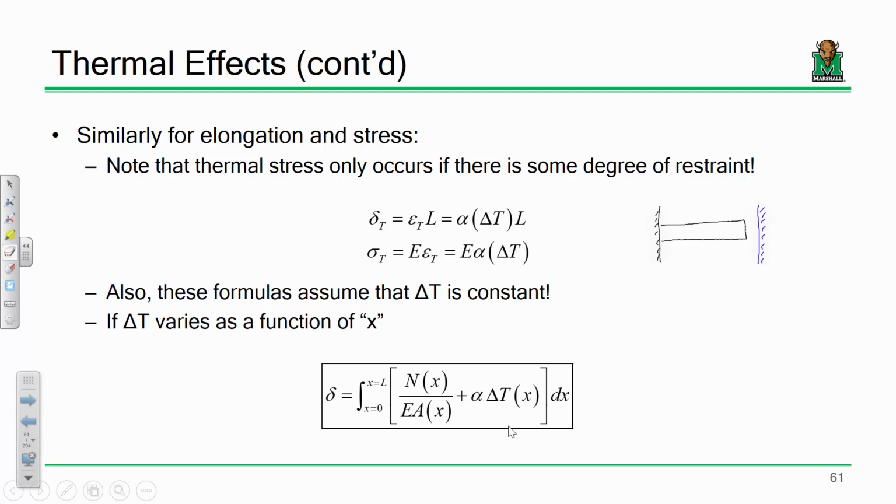This is my expression for deflection. Okay? Now, you agree I can split this up into two integrals, right? The integral of the first fraction plus the integral of this, right? Let's look at that. Does our bar in this problem have a constant area? Does it have a constant load, a constant mechanical load? Yeah, it's just P, right?